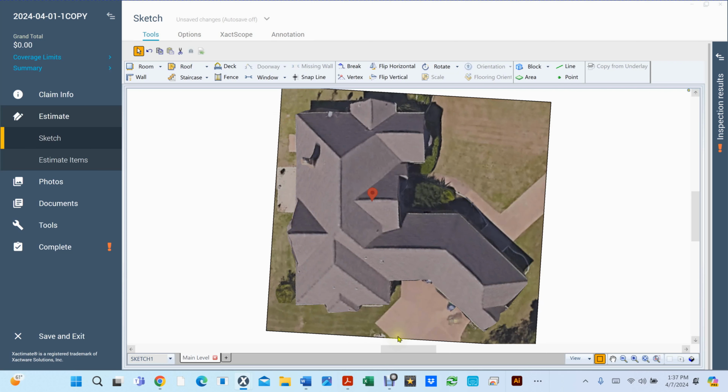So now we're going to hit the S, which is your snap line, and now you can see, look, here and here it lines up, here and here it lines up. So we have a pretty good alignment. While I have this here, I'm going to go ahead and put a snap line right here, because that's where I want to start my sketch.